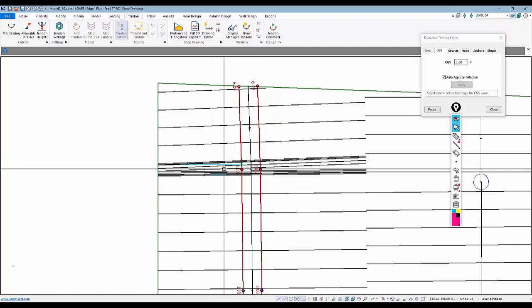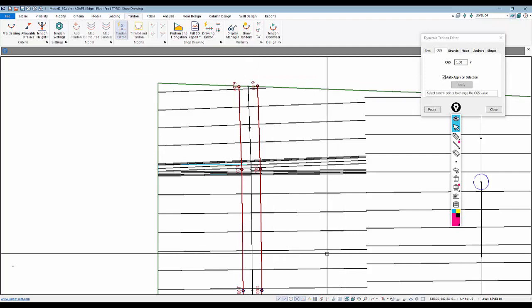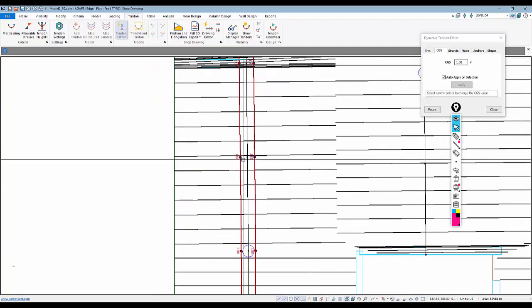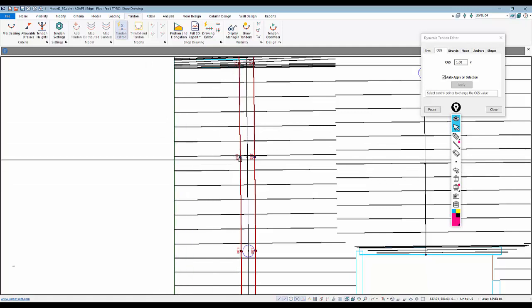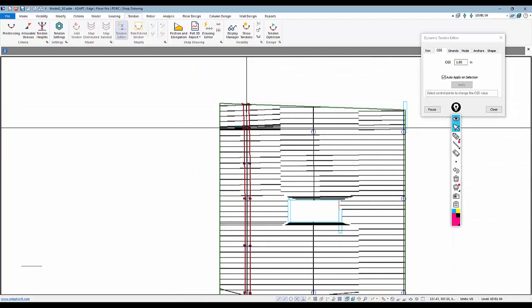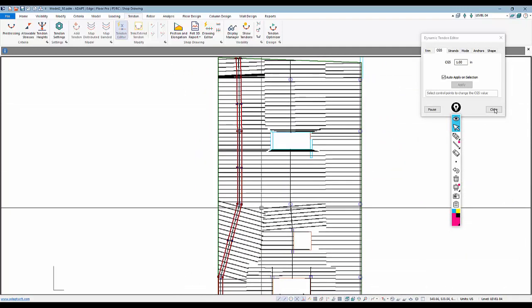So if this is a 12-inch slab, you have 11 inches from the bottom here and 6 inches from the bottom here. If you look at an interior span, this blue point is the low point, so that's from the bottom up. Remember, if this again is a 12-inch slab, this is 1 inch off the bottom of that 12-inch slab. And this is how we would define our cables in that case.